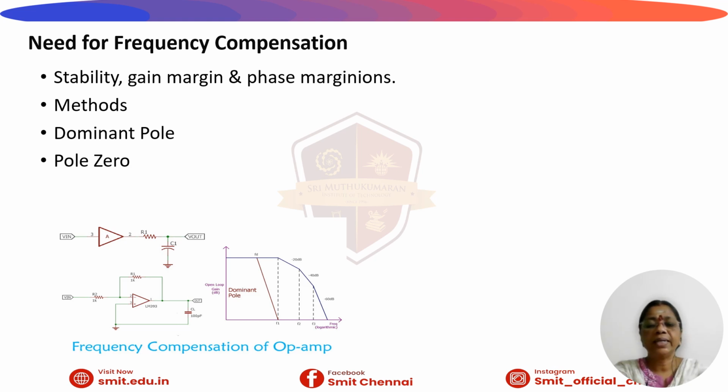the amplifier to settle, particularly to prevent unwanted oscillations when negative feedback is applied. This is because the internal op-amp stages have parasitic capacitance that creates multiple poles, that is the points at which the gain drops and the phase shift can reach 180 degrees while the gain is still high, which turns negative feedback into positive feedback.